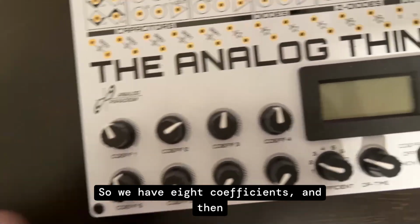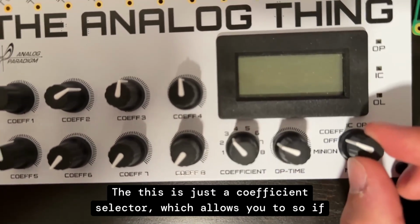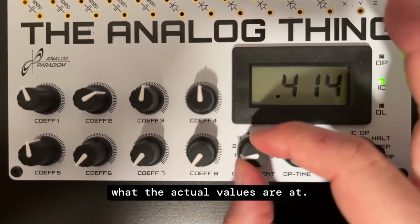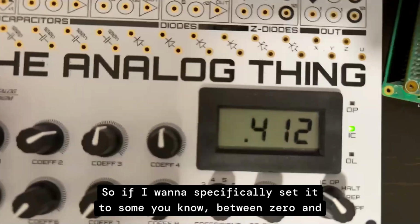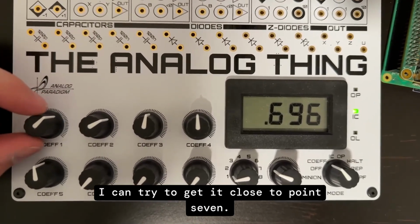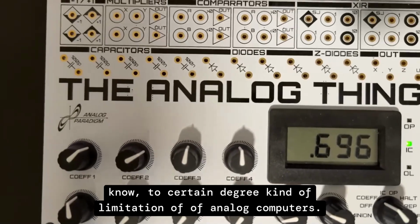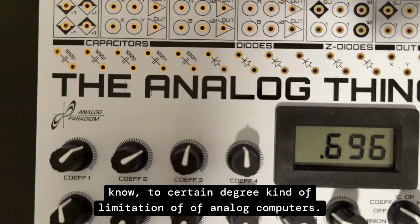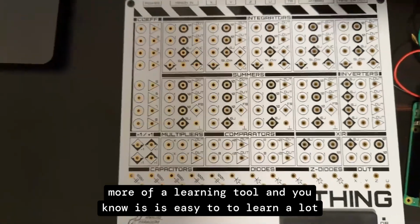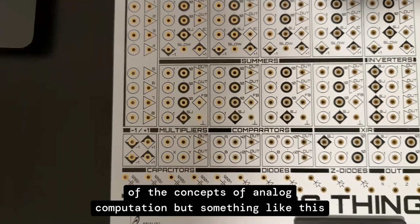So we have 8 coefficients, and then this is a coefficient selector. If I turn this on to coef, I can see what the actual values are. If I want to set it to something between 0 and 1, here you go. I can try to get it close to 0.7. And this is already showing, to a certain degree, a limitation of analog computers. This board here is really more of a learning tool, and it's easy to learn a lot of the concepts of analog computation.